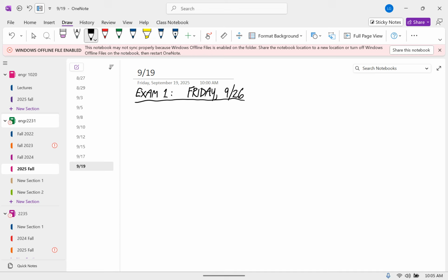And it's a surface, which means that if you specify two variables, you get the height of the thing. That says that at most you need two properties to specify the entire state. And it turns out that when you're at saturation, which is undergoing a phase change, you only need one property. So let's talk a little bit about phase change.